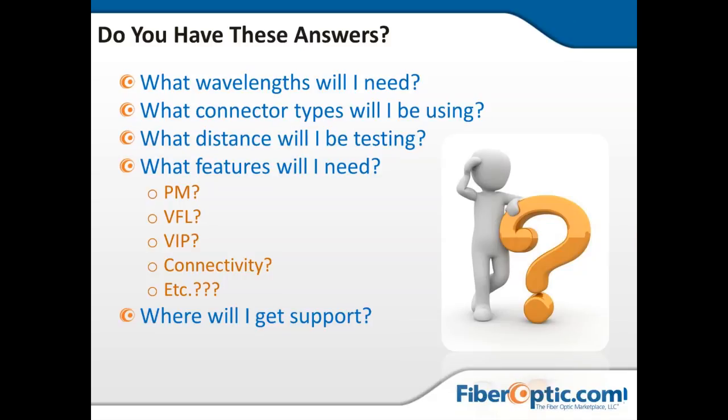There should be an absolute amount of power that is expected to be coming through there. And if you don't see that, then you need to start to go through a series of additional tests. One of those might be seeing whether there's any damage or breaks in the fiber. So step one was the power meter. Step two became the OTDR.